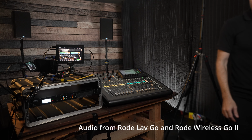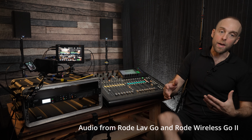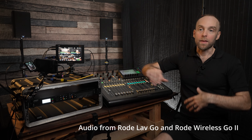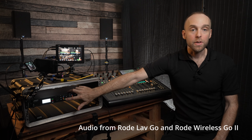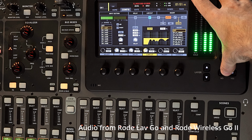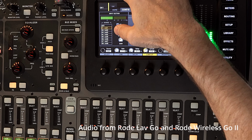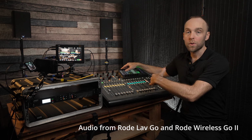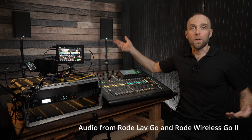All right, so that's a good level for this room, for this space. And now I've got the best of both worlds. I've got healthy input gains on my meters here on the wireless receiver. I've got healthy input gains hitting that negative 18 dBFS, which equates to line level here on the Behringer X32 console. I'm sending out at unity so my faders aren't cutting or boosting, and then we set the speakers to a good volume for the room.